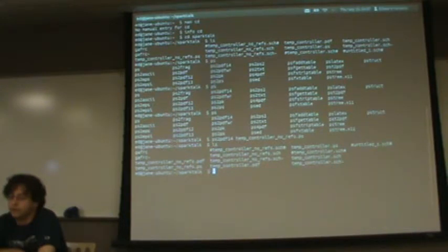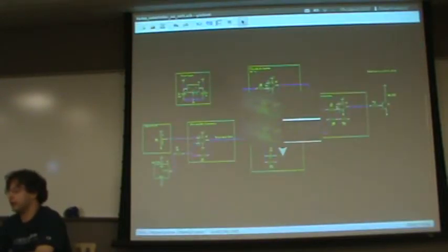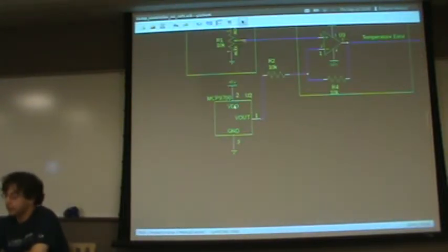Let's say you wanted to do something different. Let's say you don't want to just use the basic components in the library for gEDA. Let's say you have an exotic temperature sensor that you found on the internet and you wanted to make a schematic for it. I already did that with this symbol. So I'm just going to run through how to make symbols very, very briefly.